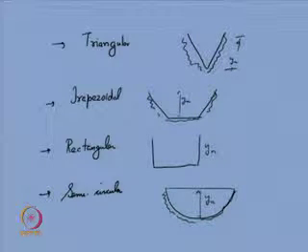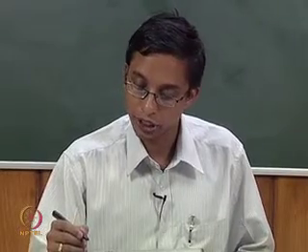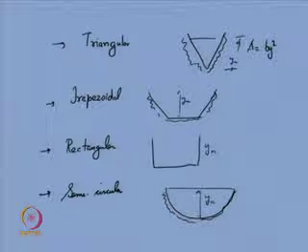Now, there is no need for me to further, you know that for such triangular channels, we have seen earlier also in various parts of the course, in the triangular section, if side slope is 1:b, then you can give your area as A is equal to b y square, your wetted perimeter P is equal to 2y root of 1 plus b square.